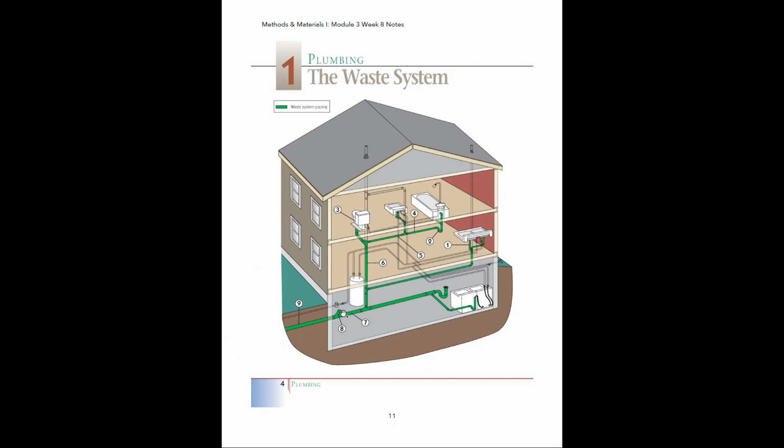And then this little Y-shaped section, number 8, is known as a clean out. Sometimes you'll see those if you go down in your basement and look at your plumbing. It's like a little cap that you can unscrew, and if for some reason you get a clog in your drain line, if you get a plumber out there, they might unscrew that and run a plumbing snake down through it to unclog anything that is blocking off this waste system.